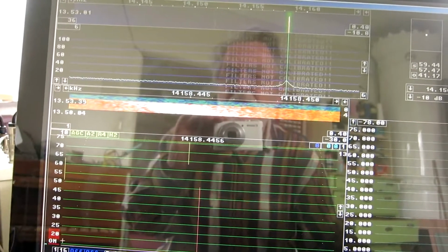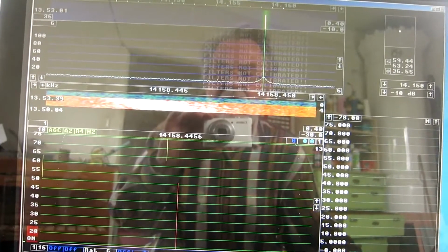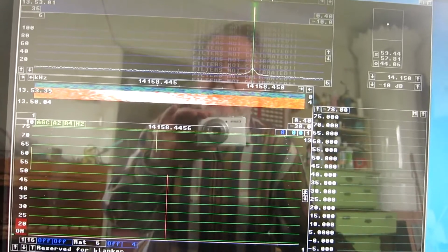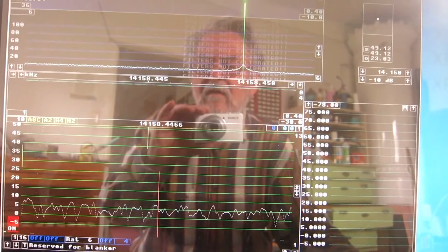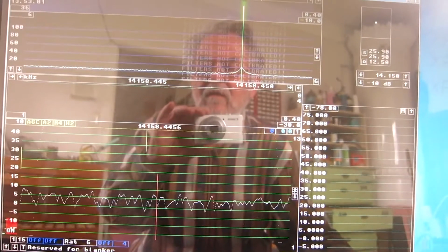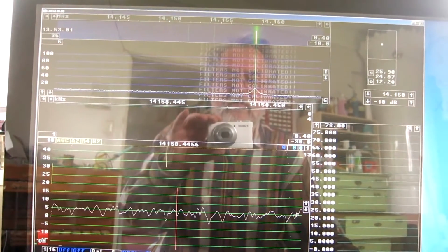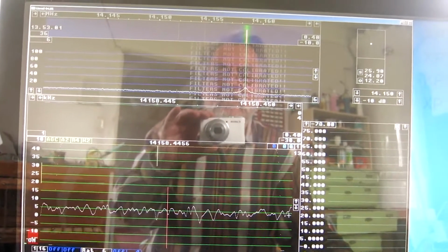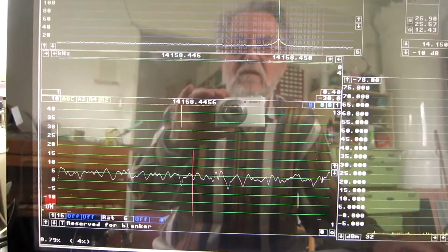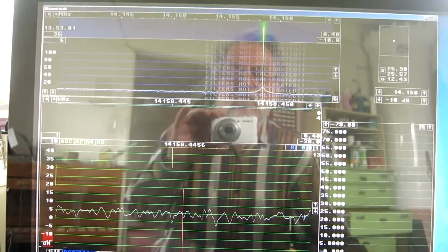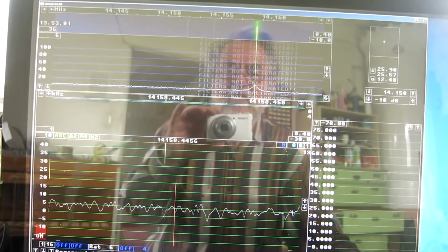And adding 30 decibels here means minus 10 at this point. Like that. So now I added 30 decibels. So you can see at something like 5 Hertz from the center frequency, the noise was reduced by 30 dB when I removed the feedback.